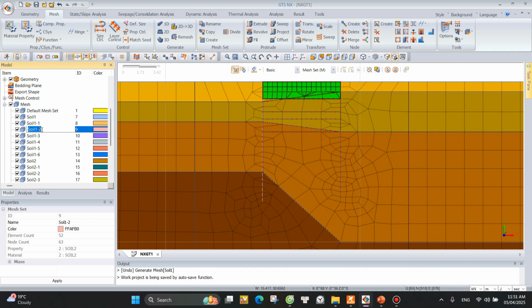So you have the first one, and now this is the excavation one. So you click F2 on the keyboard, and then use excavate one, right? Or you can quickly type X1. So it means excavation one, layer one, and you enter. So this means now this one is excavation one. If you turn off, you don't have it. If you turn on, you have it.